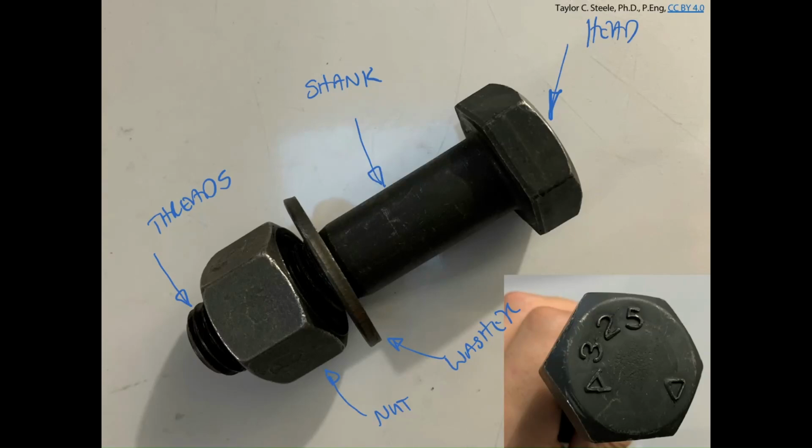There are some variants of different structural bolts. This one, you'll notice that the primary difference between the bolt that just passed around and this one is that there's no shank on this bolt. It's threaded all the way through the entire length of the bolt. That's because if you have different plate thicknesses, you might want to be able to tighten it up really small and have the ability to accommodate the additional plate thickness without having to worry about how long the shank is.